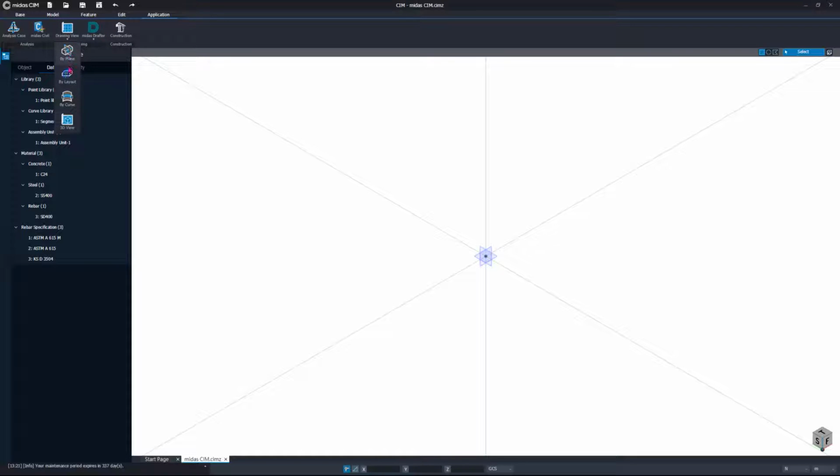This is also to organize the cutting view that we have created before. You can click cutting view based on plane, layout, by curve, and 3D view. So after you create this one, for example, if you want to create the biplane and 3D view, the results will be shown in the Midas Drafter. Okay, so for example, if you click on the Midas Drafter, you will have to wait a little bit.